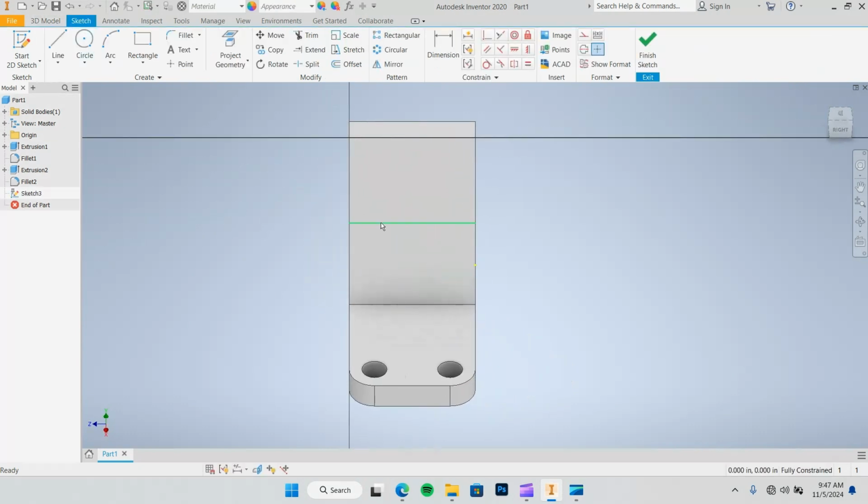So I'll create a new sketch on this surface, select my line command, locate this center point. The moment I drag my mouse pointer to this midpoint of this 3D model, you see it's highlighted green. You see a green dot over here. It tells me that that is my center point of this whole rectangle you see up there. So I'll point it on it and drag my mouse pointer 90 degrees down, 3.2 units. All right, so I'm done.